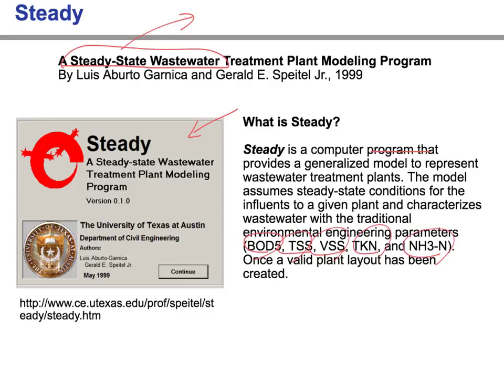As I mentioned, this is just a program for steady-state modeling and steady-state process simulation. Once a valid plant layout has been created, we can use Steady to predict how much BOD can be removed and how much TSS can be removed, something like that.